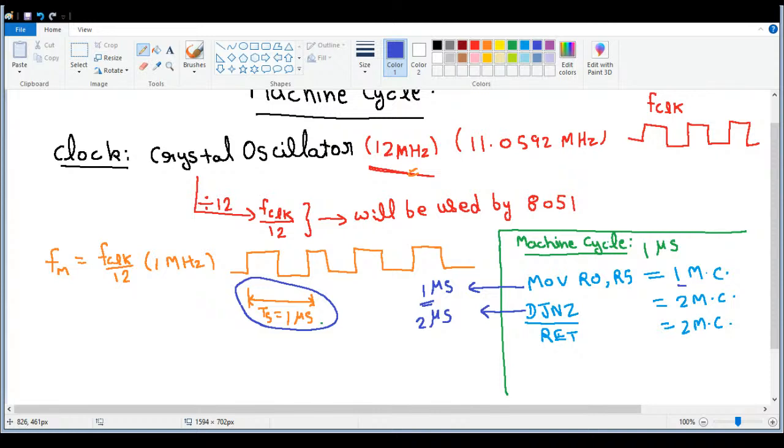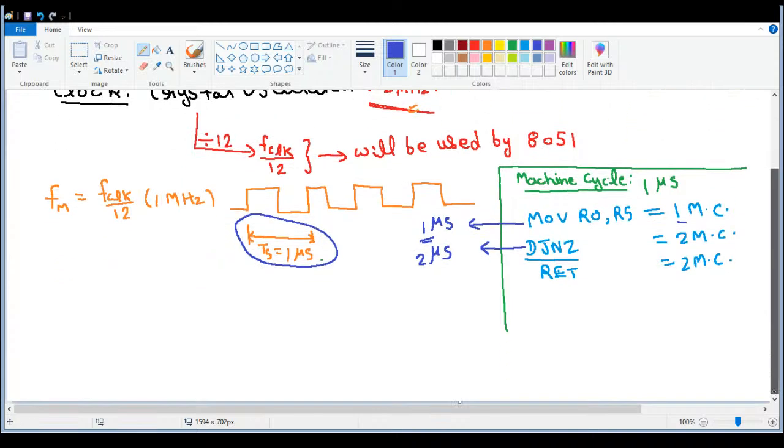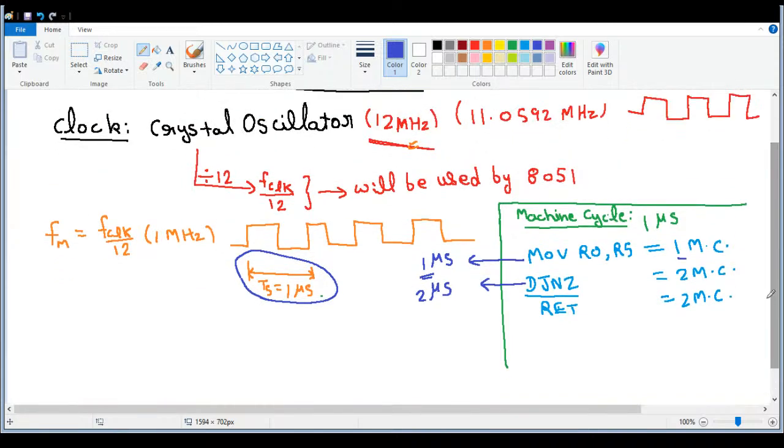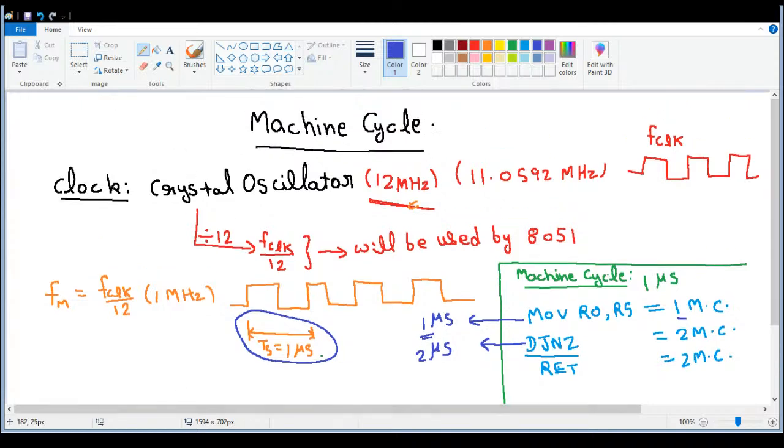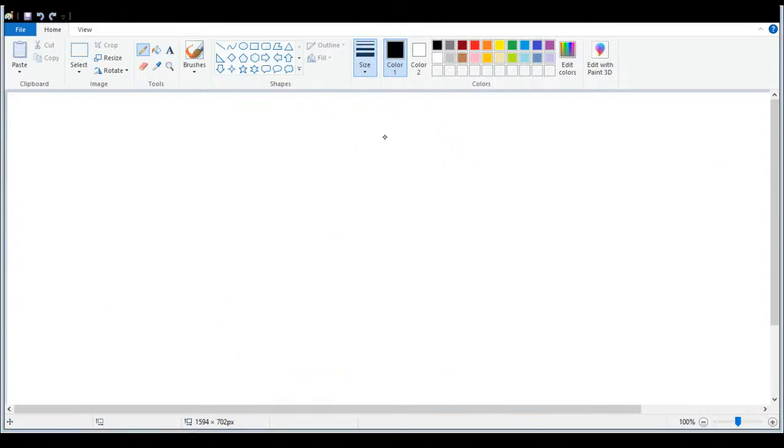Because we should know the time taken by these instructions in advance, so that we can optimize our program accordingly. Okay, so this was about machine cycles. Now the next thing we are going to talk about is the delays, or sometimes also known as the loops. We will be talking about loops within this assembly language, or calling subroutines, and also.